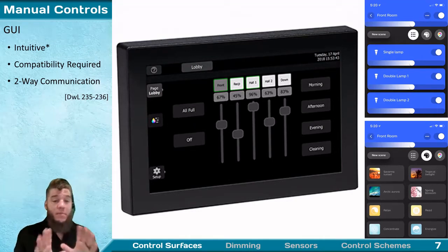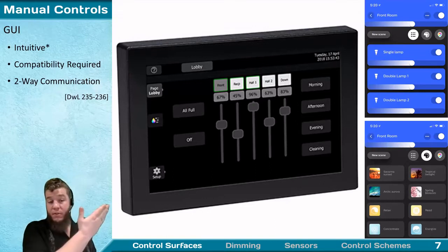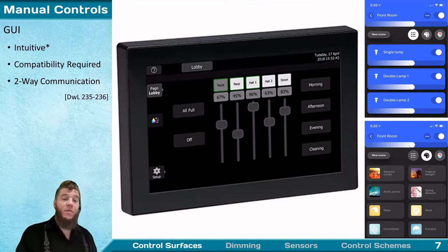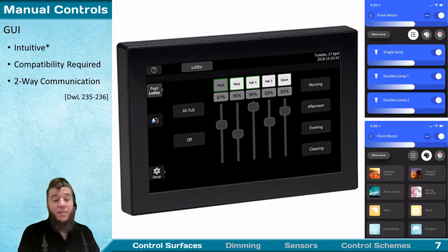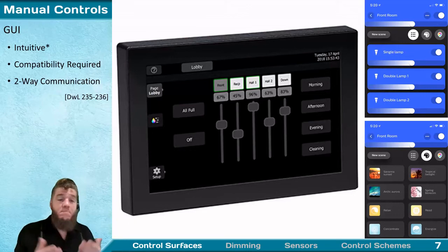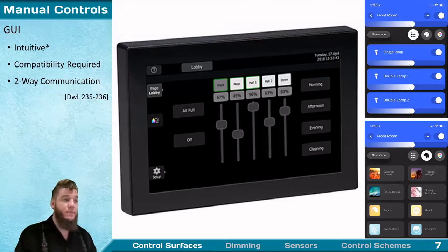End user touch screens oftentimes aren't that appropriate for a variety of architectural settings, because first off, you have a configurable display. So, there's a big question there of whether or not you want that much capability in the hands of your occupants. Depends on the type of space, depends on who you expect in the space, right? If it's a public facing space, this is probably inappropriate. If it's a private space, then you're more likely okay. You definitely need to be able to lock these down. And also you have durability issues with touchscreens over the long term. And naturally, the last concern is the cost associated with this. So you definitely need this to be in a space that really justifies the use of a more advanced control system.